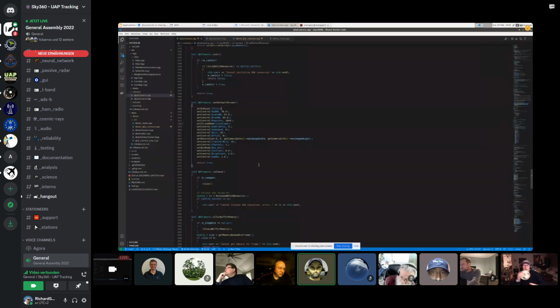Yeah, but you should try also to set the USB speed. That could also help. It's set in here. Oh yeah, I missed that. What is it set to? Zero should be unlimited, like the maximum. Unlimited, yeah. It's set in here. Here you state exposure is 2000. I think it's microseconds, so it's 2 milliseconds. Yes, it's microseconds.